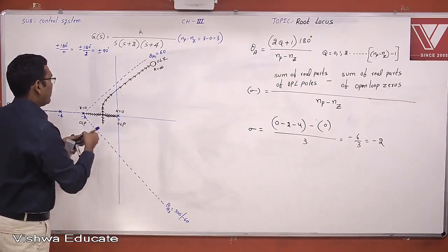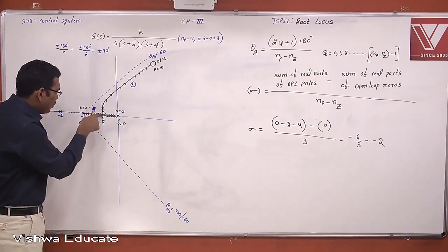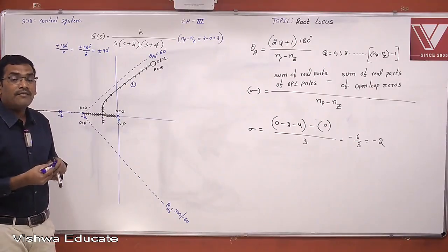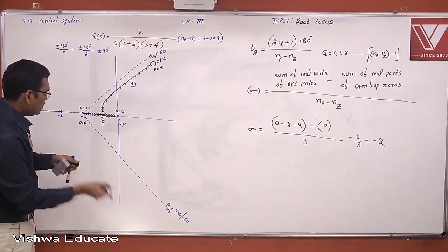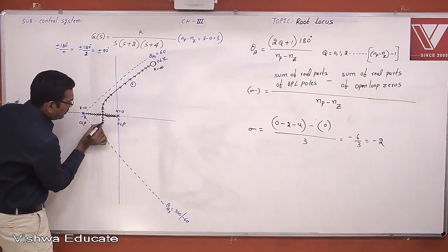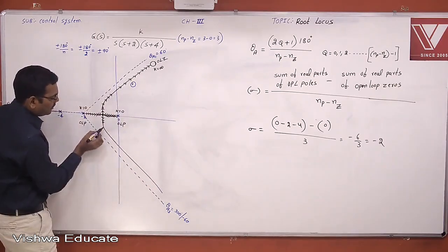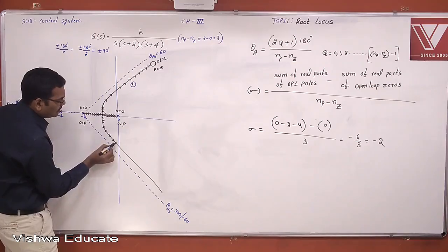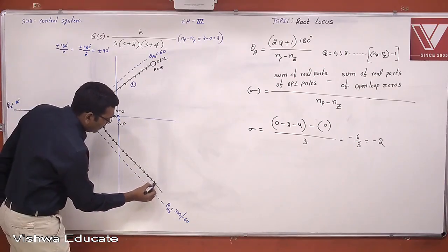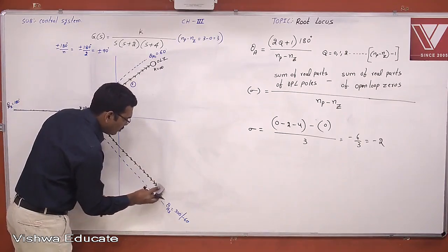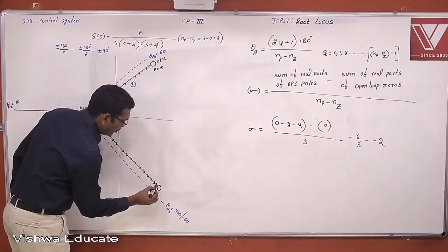Now this is one complete root locus branch first. Next, the pole is leaving at minus 90 degrees, and where will it go? Is there anything showing the direction? As k is changing, the closed loop pole is moving in this particular direction, because that direction is given by the angle of asymptote. It will meet the zero at 1, 0 in this direction, because this is the direction that approaches infinity.